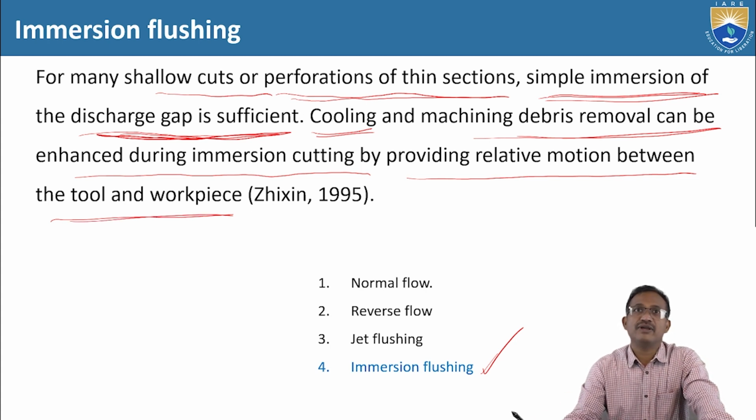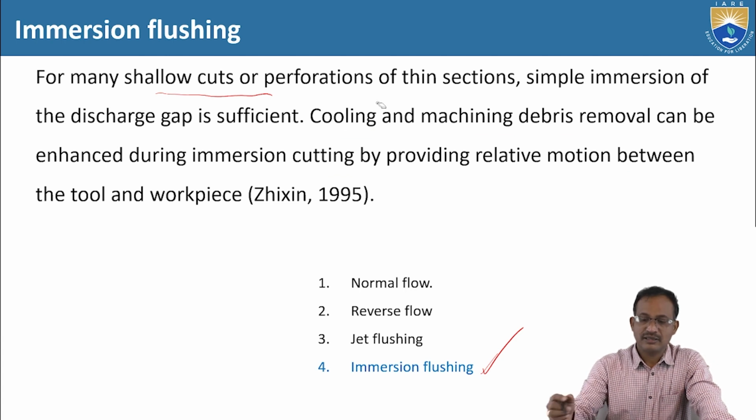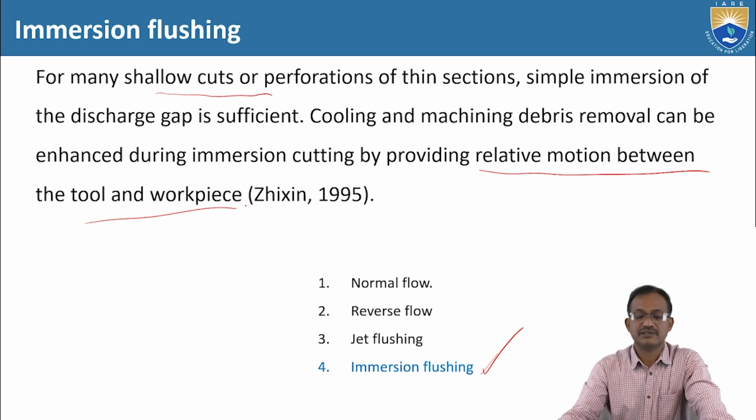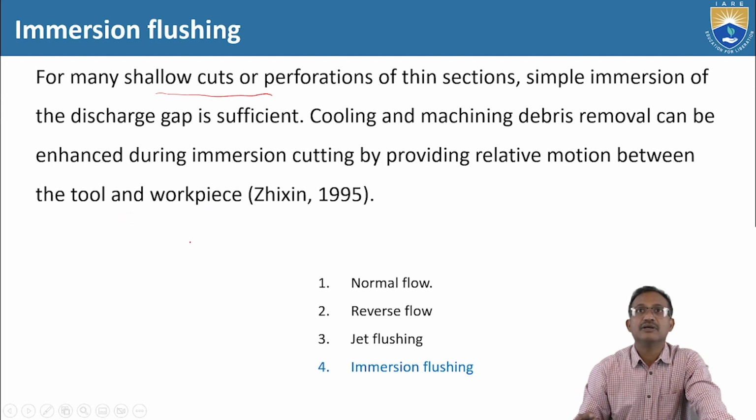While we immerse completely, what will happen? It constantly flushes the debris. So that's why it will enhance the relative motion between the tool and the workpiece. So finally, the machining will be good in this immersion flushing.